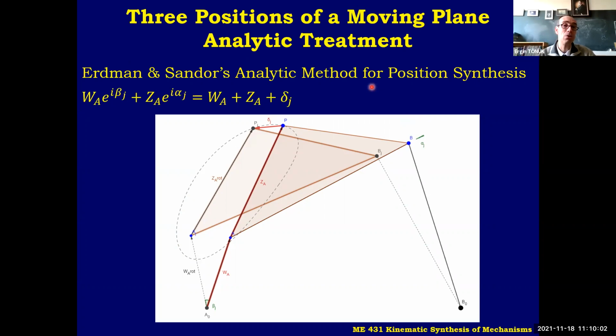But one of their contributions is, as known by their name, Erdman and Sandor's analytic method for position synthesis, which is actually, if you like, a vector equation, or you can represent it by complex numbers. Now, let me try to explain this equation, which is very, very handy and very, very useful.